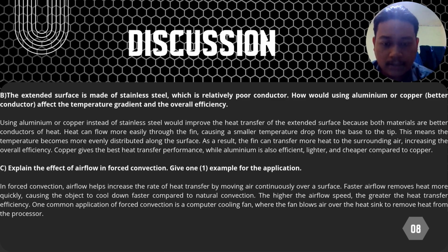Replacing stainless steel with aluminium or copper enhances heat transfer due to their higher thermal conductivity. Thermal energy moves more effortlessly through the fin, minimizing the temperature decline from its base to the tip. Consequently, the temperature distribution across the surface becomes more uniform. This allows the fin to dissipate more heat into the ambient air, raising the overall efficiency. Copper delivers peak thermal performance, whereas aluminium offers a highly efficient, lightweight, and cost-effective alternative.